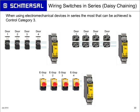Whenever you wire standard electromechanical safety devices, the most that you can ever achieve is a Control Category 3 on these particular devices. The main reason behind that, whether it's a coded magnetic, an E-stop, or a keyed switch, is that you don't eliminate some of the mechanical failures, but also because they're wired in series, you lose some diagnostic capability.